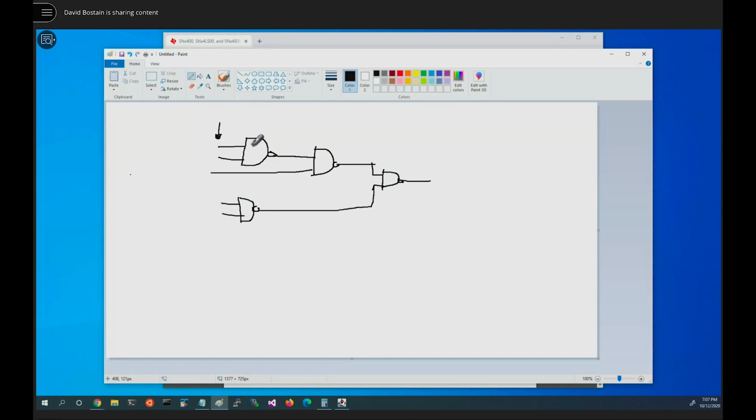If I could, then we know the result of this particular NAND gate is going to be available here at 22 nanoseconds, if we call this 0 nanoseconds here. This guy is going to be 22 nanoseconds after that, but he actually saw this guy at 0 nanoseconds.